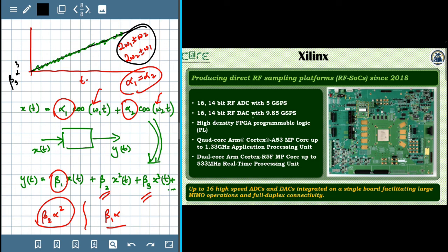And that just means that if you are operating with first or second Nyquist zone of the DACs, you can safely operate this device to produce carrier signals with carrier frequencies as high as 18 or 19 gigahertz.